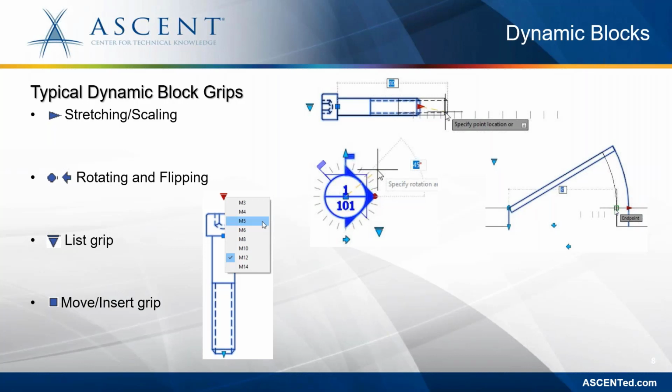Then there is the list grip, which opens a list of options that are defined in the block. You can see that here on the screen. This is the list grip, and it displays all the different options of the bolt. So it contains a list where you can select the standard sizes for the bolt.